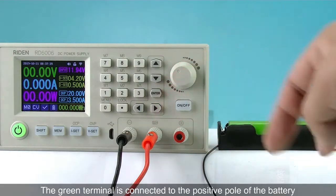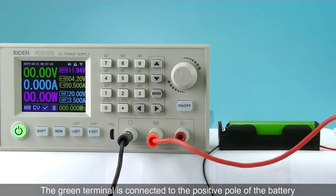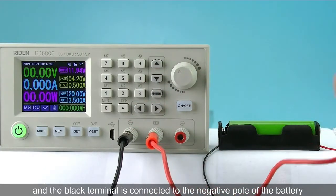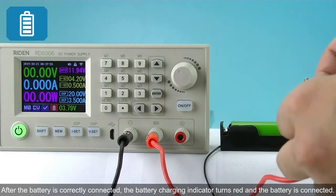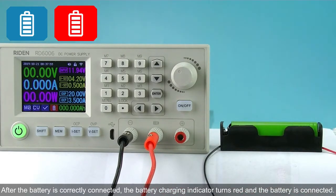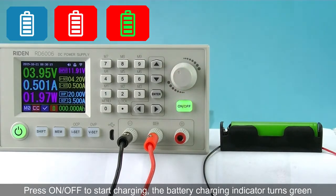The green terminal is connected to the positive pole of the battery, and the black terminal is connected to the negative pole of the battery. After the battery is correctly connected, the battery charging indicator turns red and the battery is connected. Press On/Off to start charging. The battery charging indicator turns green.